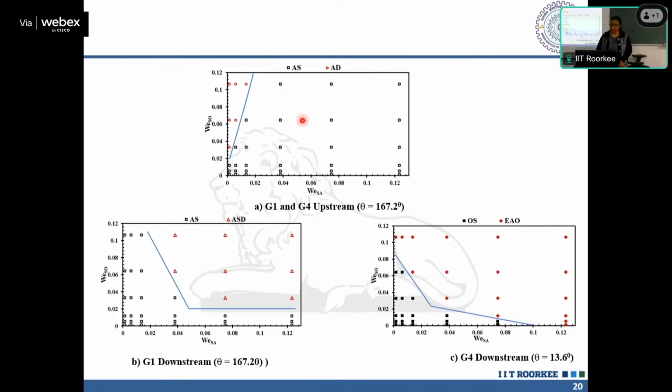If it remains that way, the only thing that changes is a sudden change in area. So what will happen is that we have slug and droplet formation enhancement, and that's all. Okay. When we have a change of wettability combined with the change of area, then what happens? We get an entirely different set of flow regimes. So here we have air, aqueous slug and aqueous drop.